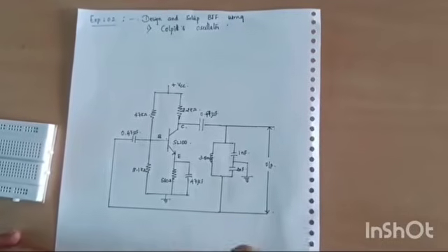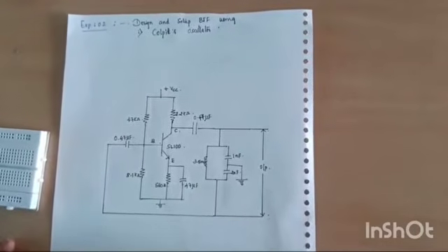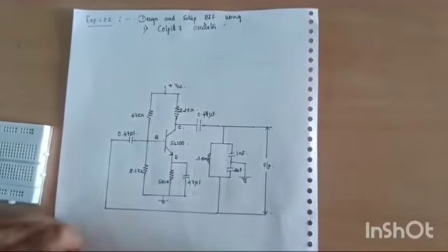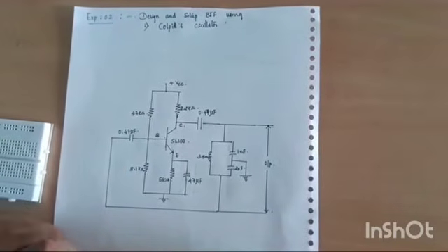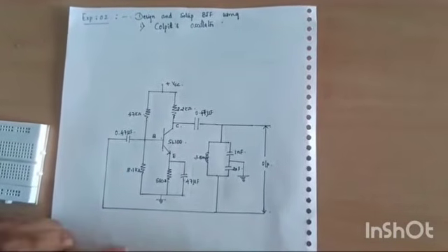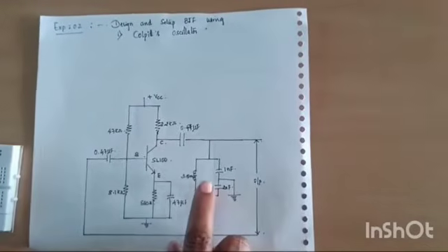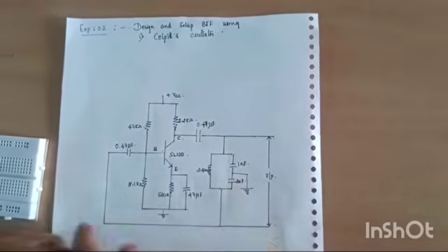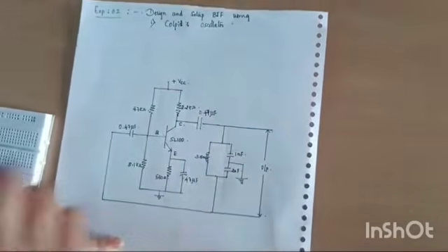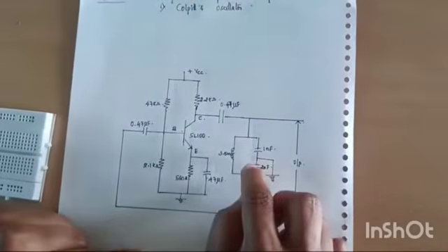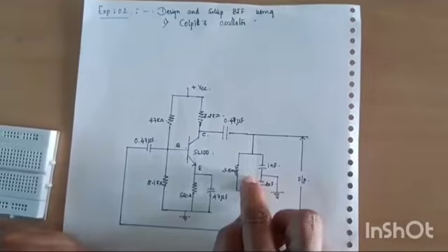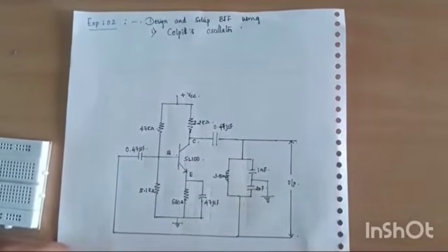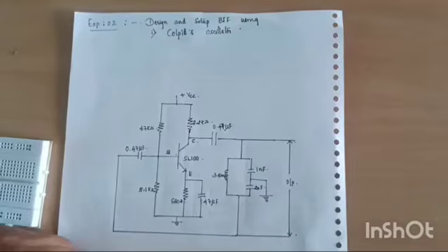Without giving input, how is it producing a continuous oscillation? Because of the thermal noise present in the circuit, which helps to provide a little bit of voltage fluctuation. That is produced using this tank circuit. Part of this voltage is fed back to the voltage amplifier circuit. Whatever losses happen in the tank circuit will be compensated using this amplifier circuit. This is the design of that.